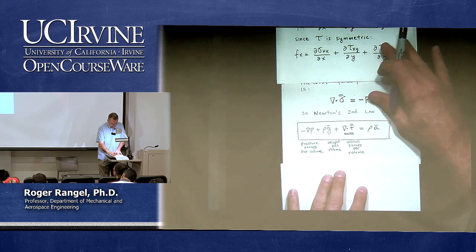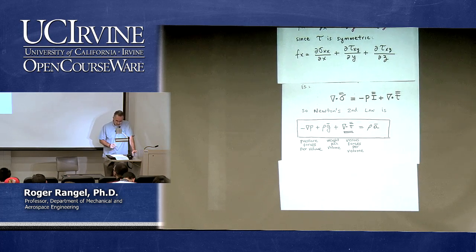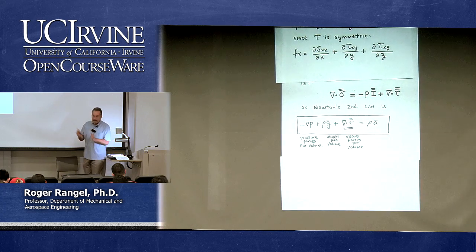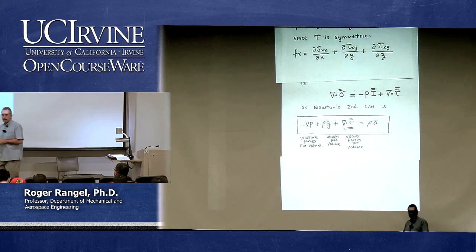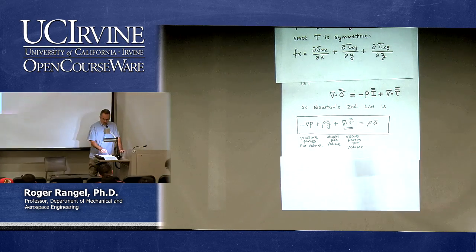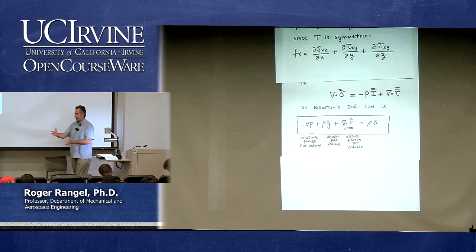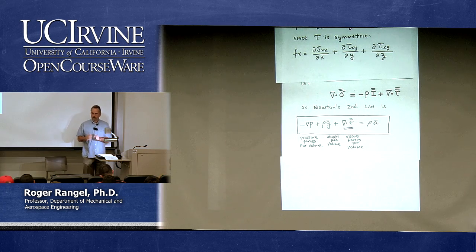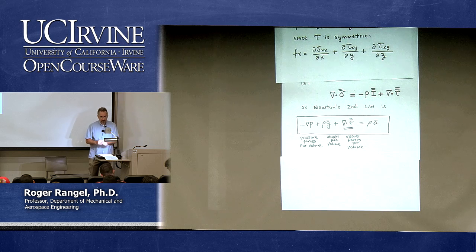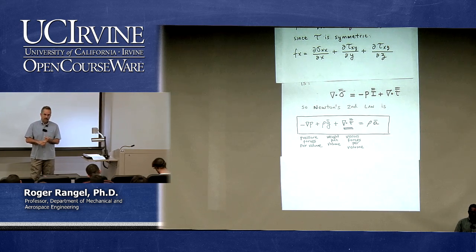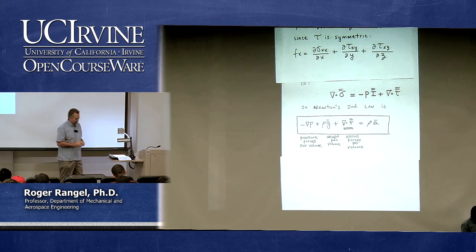So when you can label them, of course, the first one, pressure forces per unit volume. Second one, the weight per unit volume. And now the new term, the viscous forces per unit volume. That's a very general equation for the motion and deformation of a substance that moves and deforms. We're learning fluid mechanics for the first time. So the substances that we are going to be looking at are the same ones that you have been looking at up to this point. Water and perhaps air.